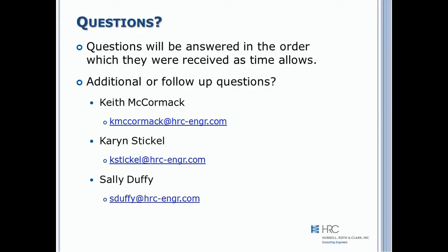Another question is, does pipe assessment have to be PACP? And what about a combined storm sewer structure assessment and repair plan? For PACP, if you are doing cleaning and televising and rating your sewers, you do have to use the PACP rating system. That is a defined way of identifying the condition of the sewers through a point system developed by NASSCO.